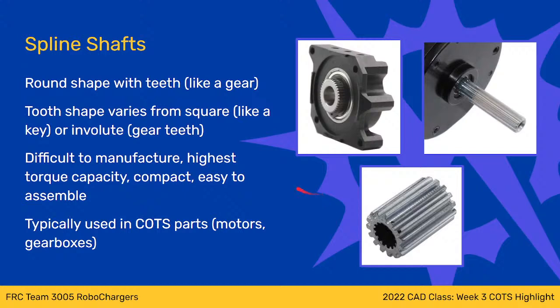You will also see a lot of splines in automotive, right? Because they are doing high volume production for a very specific purpose. So it's not a very big ask to manufacture splines there. The other thing I should mention about the spline is that this is the highest torque capacity shaft type available. The tooth form is optimized to not fail under load. Generally speaking, a spline shaft will just shear right across. You have to break the shaft before it'll strip out. You can't really strip them.